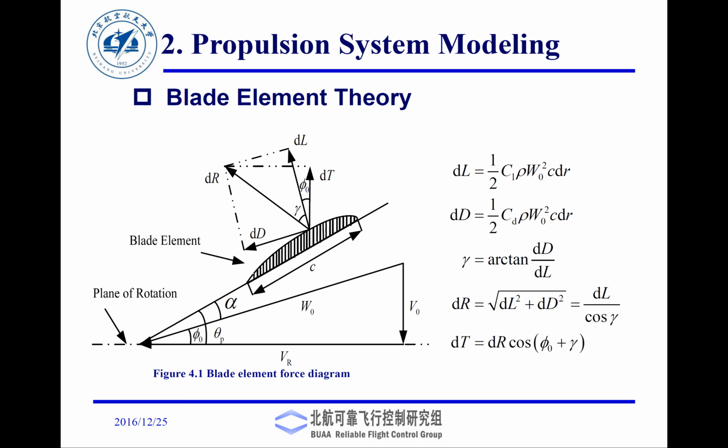You are driving, you put your hand outside and make it flat. As you increase this angle, you would notice that you are going to get more and more lift. After some time, if this angle is very high, you are going to just get drag. There will be no lift. So that's exactly what is happening. As angle of attack changes, the coefficient of lift changes.